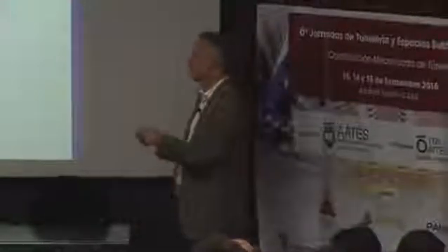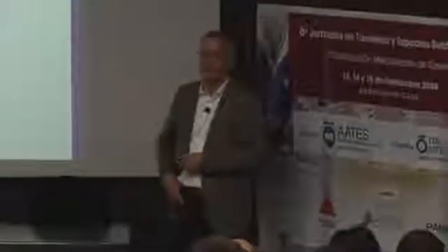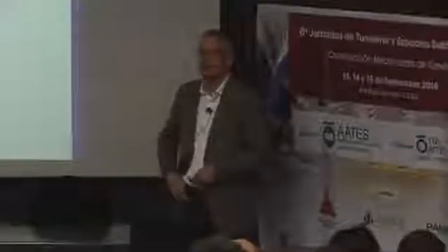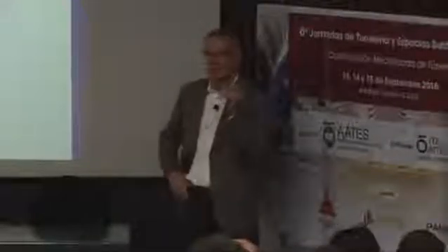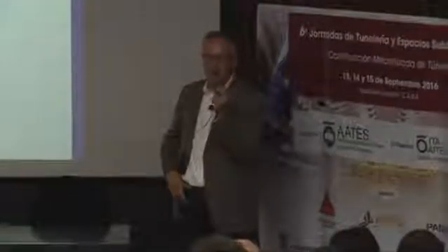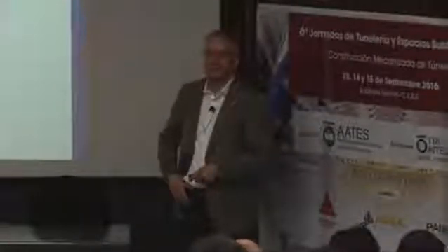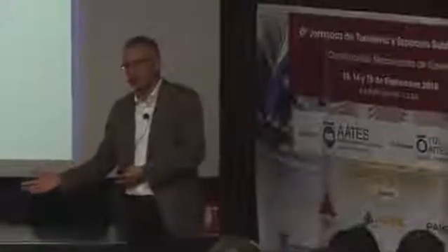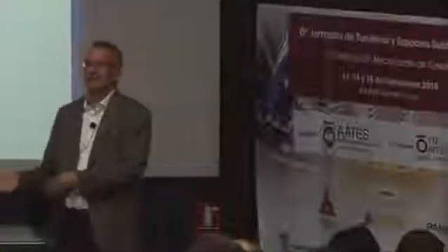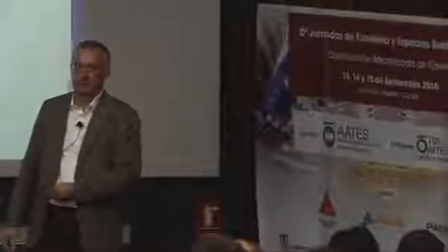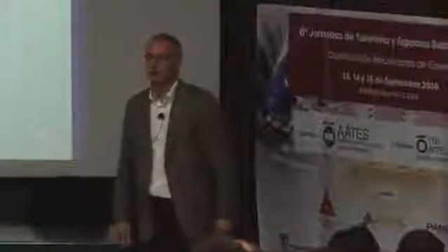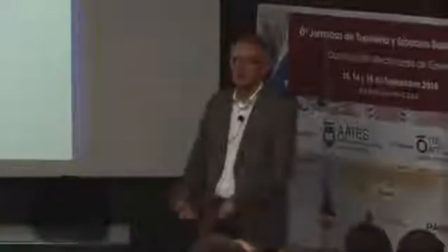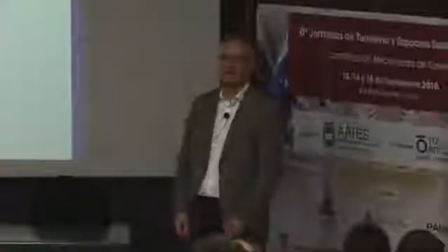That effect is actually happening on some projects where they are not even able to build a ring without turning the cutter head in the meantime in the front. So they cannot even stop for 30 minutes or 45 minutes without turning the cutter head. That creates, of course, a big problem. But they have then as well their special mixtures on Friday evenings.